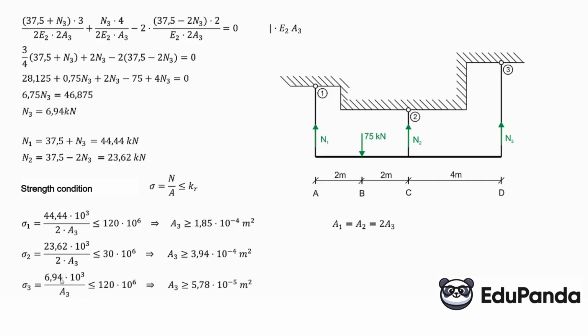Third condition, meaning the third rod. Well, here the smallest force is in it, and it is steel, so here we find that the area from the third condition, the result is 1 order of magnitude smaller. Because here, a thin rod would be enough to hold it, since the force in this rod will be the smallest. But we need to do it so that all 3 conditions are satisfied.